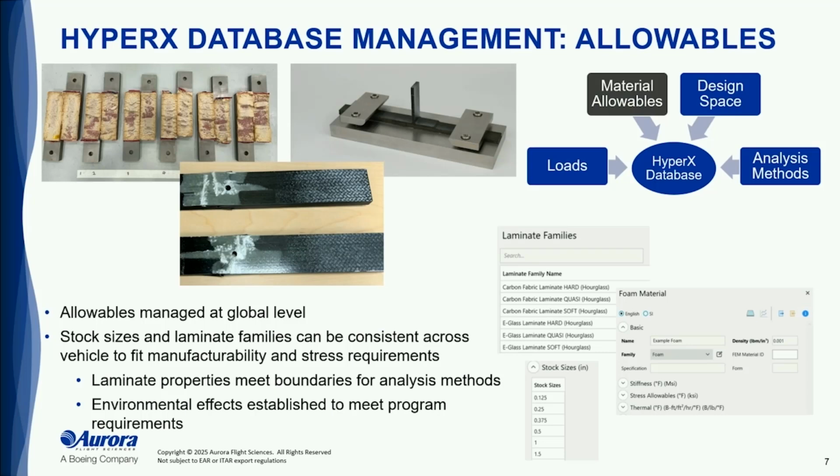On the material allowable side, like I said, trying to use maritime materials, so that includes foam cores, glass fabrics, and resin-infused systems, which are things used in aerospace, but not necessarily on primary structures or in a wide-scale approach. And Liberty Lifter being a large cargo plane, we're using a lot of these materials, and so that's where you really need to have a good control of what those allowables are and how you're considering them.